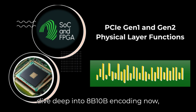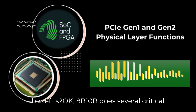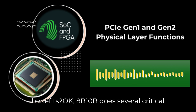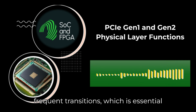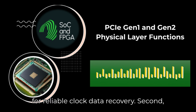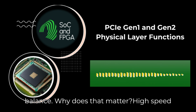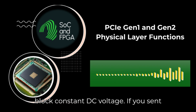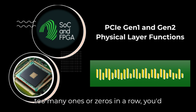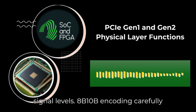Okay, let's dive deep into 8B10B encoding now, turning 8 bits into 10. What are all the benefits? Okay, 8B10B does several critical things. First, as we said, it guarantees frequent transitions, which is essential for reliable clock data recovery. Second, it ensures DC balance. DC balance, why does that matter? High-speed links are often AC coupled, meaning they block constant DC voltage. If you sent too many ones or zeros in a row, you'd build up a DC bias that could mess up the signal levels.